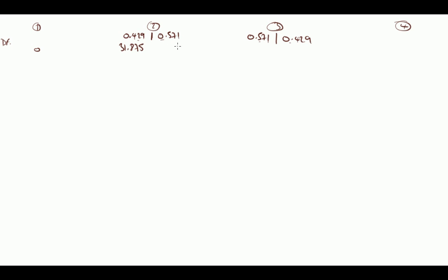They of course are connected in real life, and that's why we need to redistribute the imbalance of moment, because in real life it will find an equilibrium. And we've got minus 21.25, so an anti-clockwise moment of 21.25, and then clockwise 21.25 here, and minus 31.875 on this side of the joint, and then 0 at grid line 4, so the other end of the span.